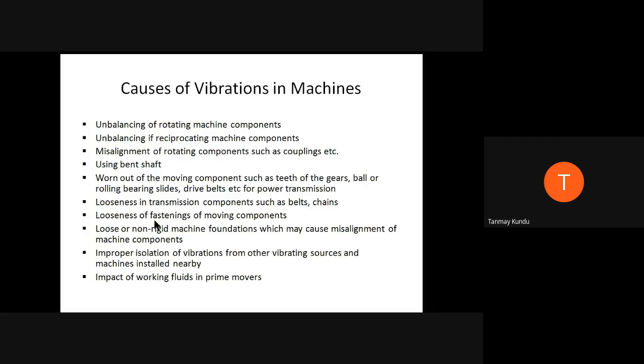Next, looseness in transmission components such as belts or chains. You can understand that you must tighten those transmission components, otherwise if they are loose at some point, that point will be subjected to vibration.